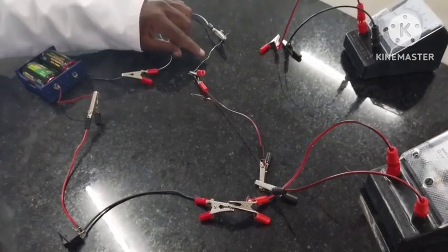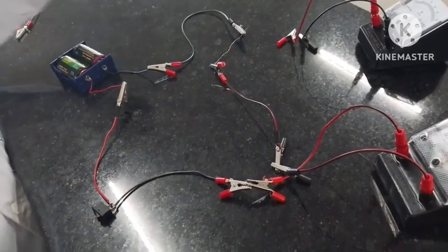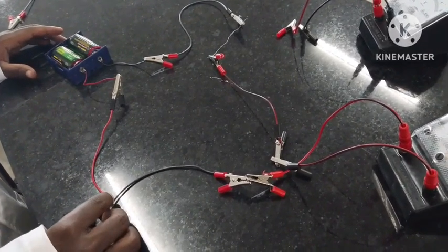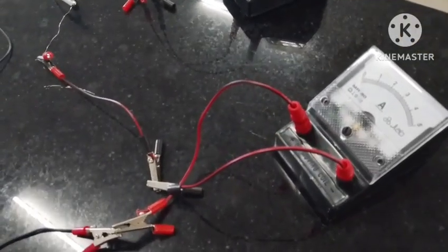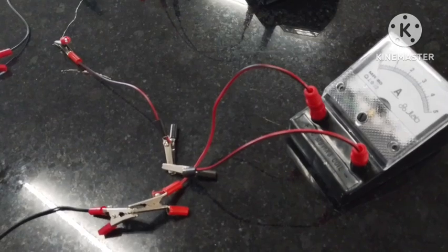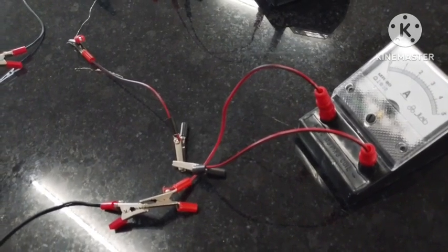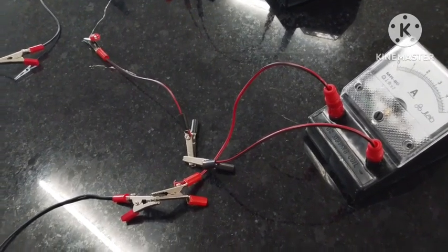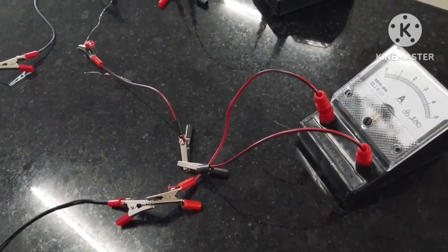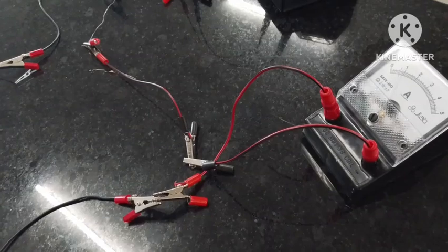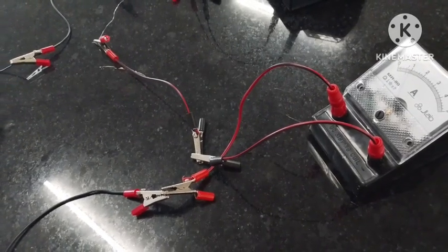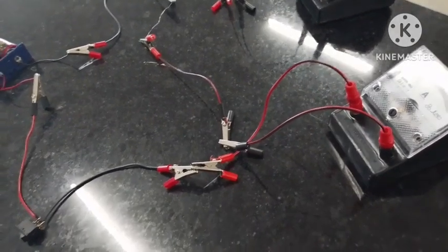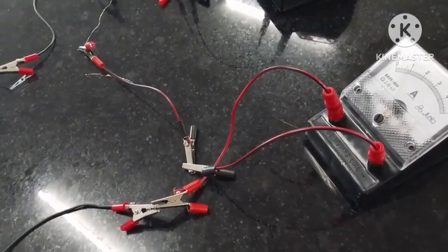But we have connected a component, and our component is a nichrome wire. So we can switch on to see whether our arrangement is properly connected. So we can switch on the switch. You can see the pointer has deflected to the positive side, meaning that our connection is just perfect. But we said for us to find resistance, we need to connect a voltmeter.